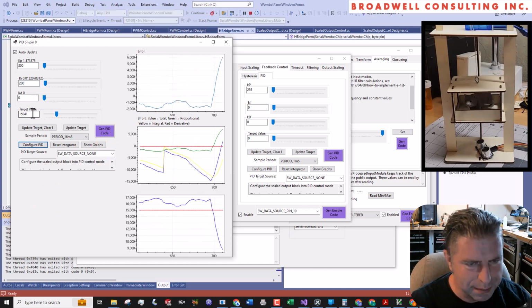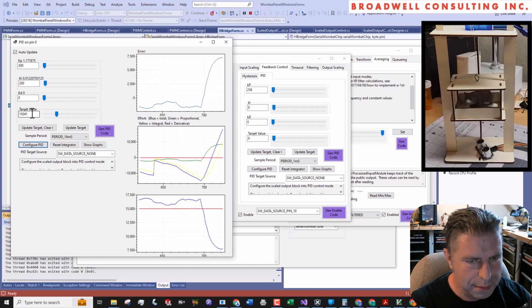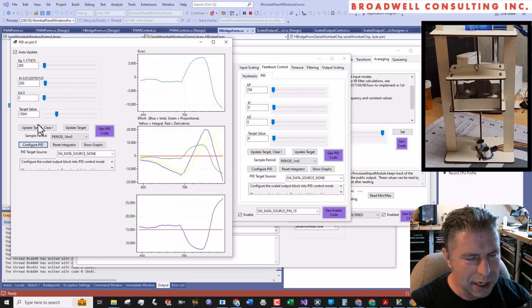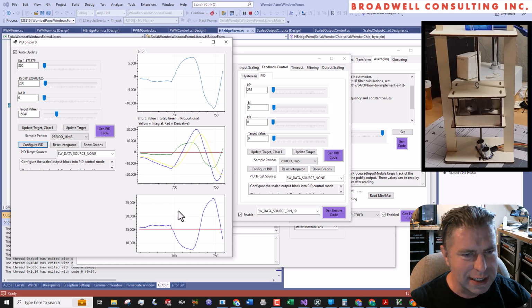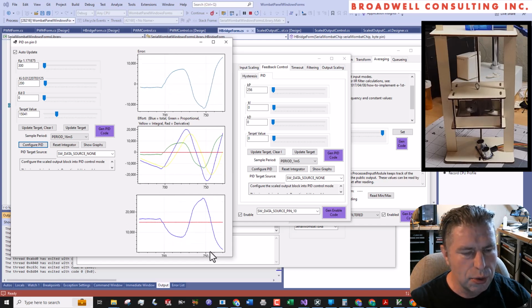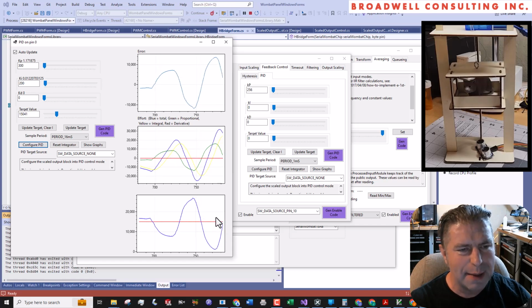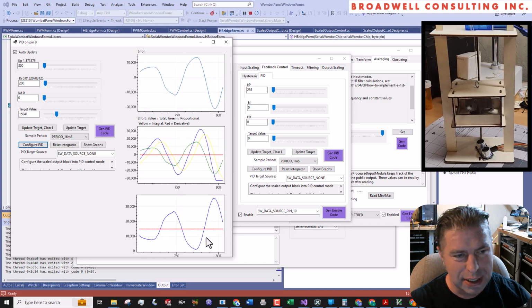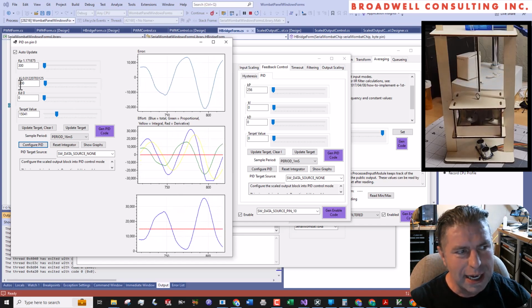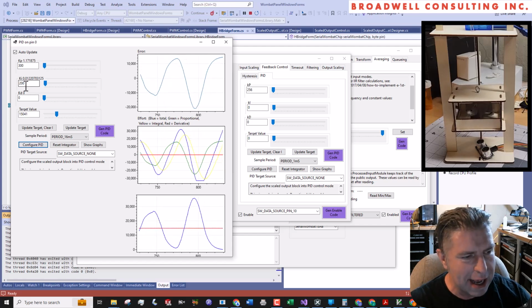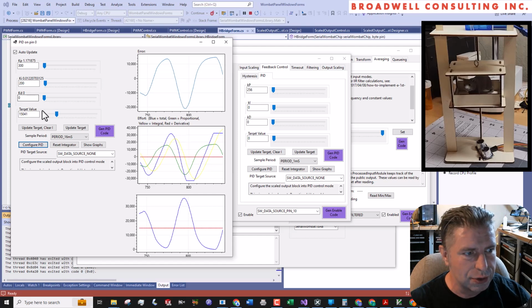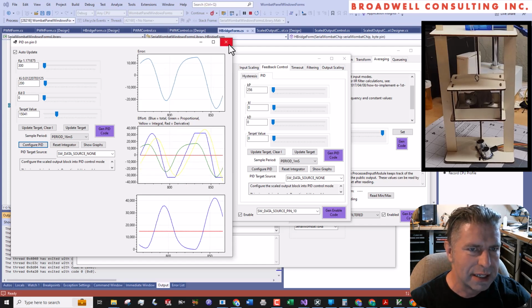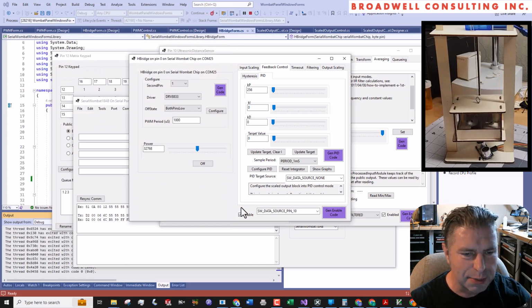Enough. And then again, we got pretty massive overshoot. Part of the problem with this particular control system is that it takes a long time to move that elevator a distance compared to the response time of the system. So any kind of an I component is almost always going to have an overshoot to it. So at the end of the day, PID is just not a very good control system for this. So let's see what else we can do.